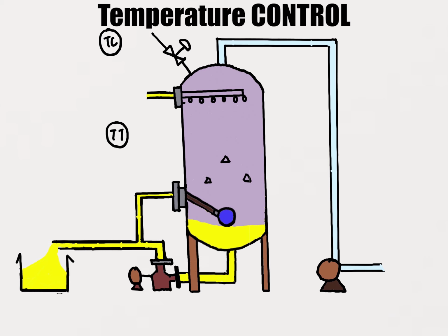During the drying process, the temperature of the chamber is measured using a temperature sensor. If the temperature is lower than 75 degrees Celsius, the control valve of the steam inlet increases the steam flow rate to raise the chamber temperature. Conversely, if the temperature exceeds 80 degrees Celsius, the control valve of the steam inlet reduces steam flow to reduce the chamber temperature.